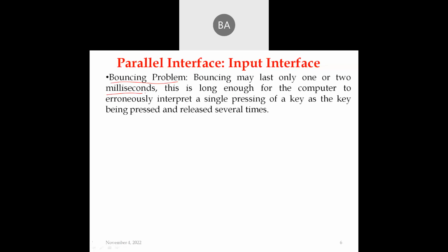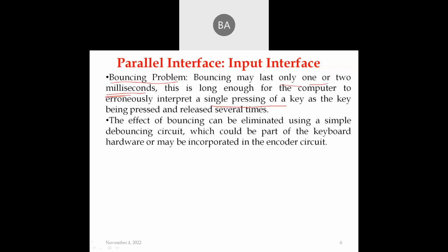So this concerns the rate at which you press the key on the keyboard and the rate at which the data is received by the keyboard interface and processed. A time gap of 1 or 2 milliseconds is maintained, and if it is not maintained properly, it results in a bouncing effect.